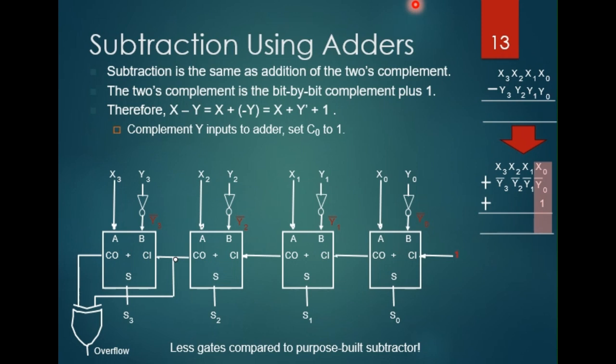The second reason is because normally a circuit will not just have a subtractor alone. Normally the circuit which has a subtractor will also need an adder. So if we can see the similarity between the subtractor circuit and the adder circuit, then we can easily accept the fact that the adder can share a lot of logic with the subtractor. So these two designs can be merged to make a configurable design, a circuit that can be configured between addition function and subtraction function. So let's see why they can share a lot of logic.